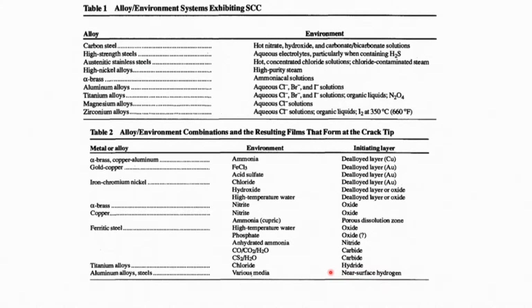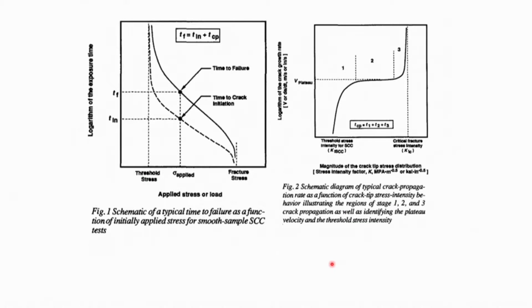The second reason is that there may be some hydride or other compound formation which is neither protective nor ductile, and is highly brittle in nature. The third reason may be some other phase formation which is porous, in contrast to the passive film which was needed to form for protection against corrosion in that environment. So, these are the different reasons for stress corrosion cracking.